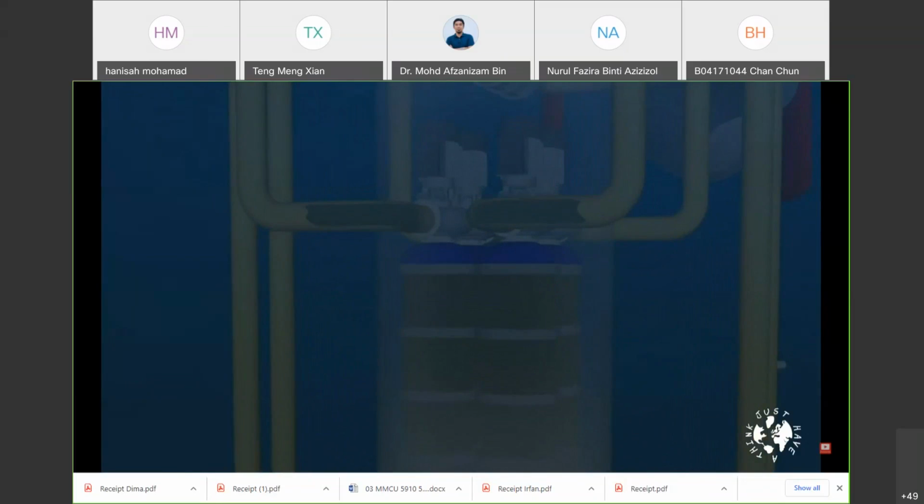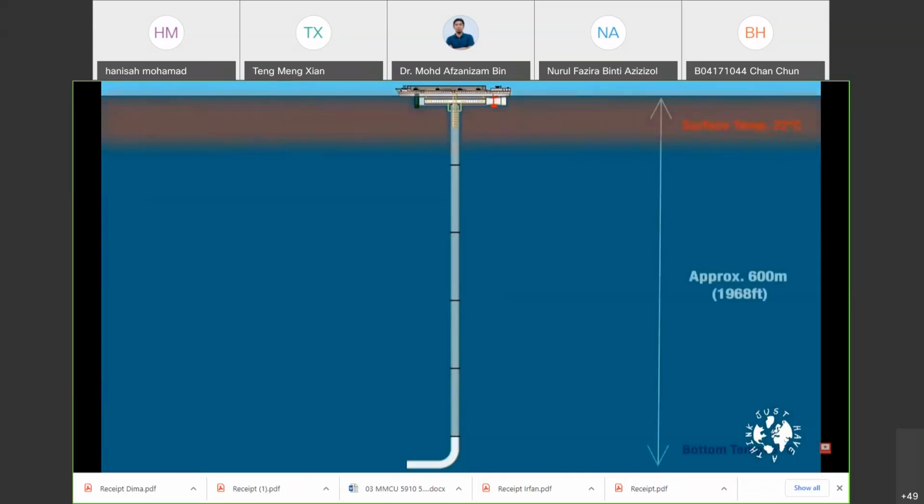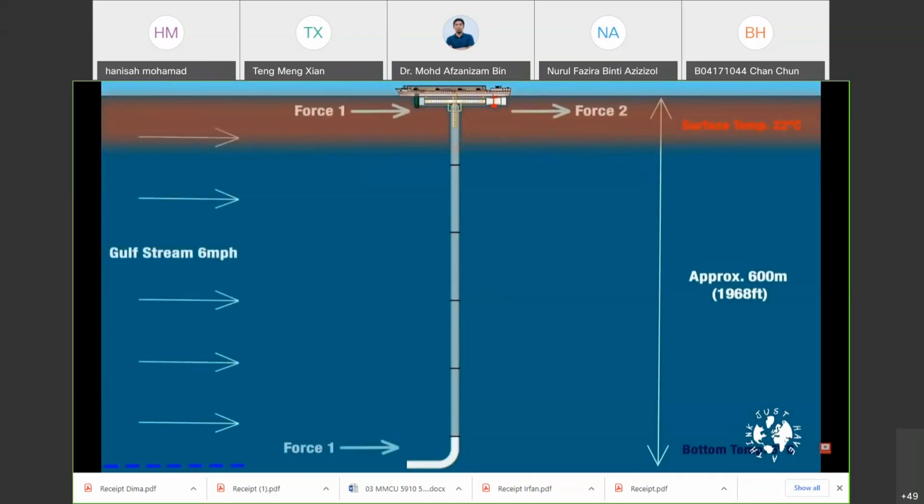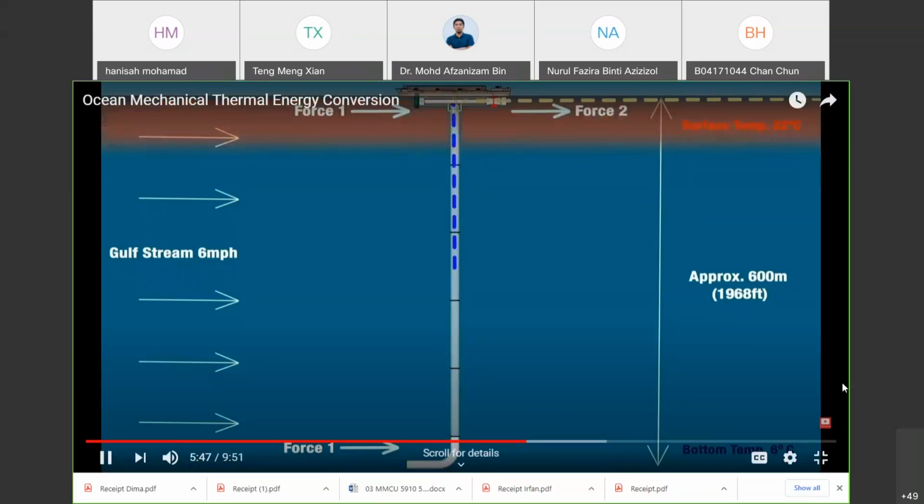Patrick McNulty's OTEC system exploits 2 natural phenomena of the Gulfstream to overcome this power loss issue. Let's quickly remind ourselves of the schematic we looked at earlier. Because there are 2 equal forces being applied to the top and bottom openings, but only a single outlet, the one on the right-hand side of the top tunnel, there'll always be a pressure differential that draws water up the vertical pipe, just like a siphon. And that means there's no need for a pump to do this job. That is a major saving in system energy requirement.